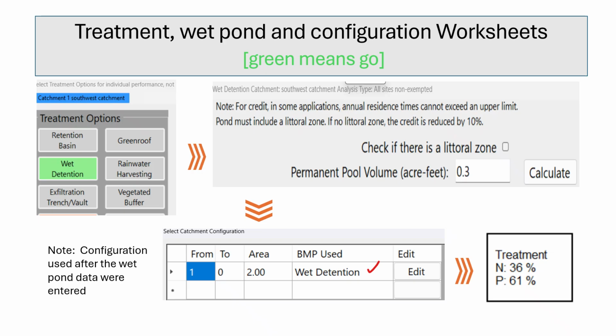For instance, our example shows that the initial wet pond alone does not satisfy either the 55/80% reduction or the 77.3, 73.7 net improvement targets. In such cases, additional BMPs, like modifying the catchment's directly connected impervious area or incorporating other treatment measures, will be necessary to achieve compliance. This specific project example also illustrates how it's possible to meet one of the required percentage removals or net improvements, but not necessarily both simultaneously.